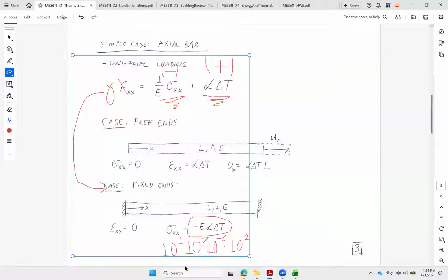So now I'm looking at 8, 10 to the 4th for my stress units. That's 10,000 psi or 10 ksi, that's getting up in a really big stress range. A lot of basic materials might be 30,000 psi for yield, 36,000 for base steel. The softer aluminums are 30 to 40,000 as well. So I can get up in the same decimal place as the yield stress just from thermal expansion if I fully constrain those ends. So what looked like really small number here for alpha, and then we add delta T, but once we multiply modulus on there, it starts getting to be a pretty significant number.